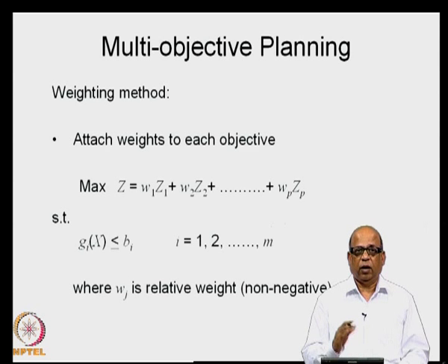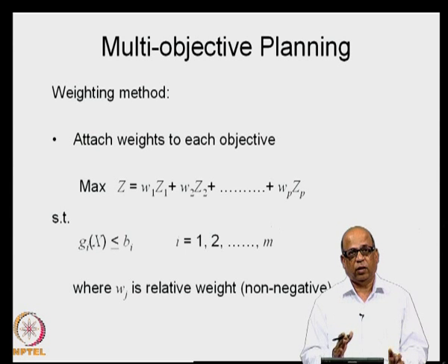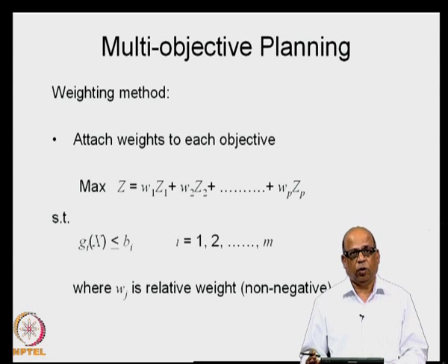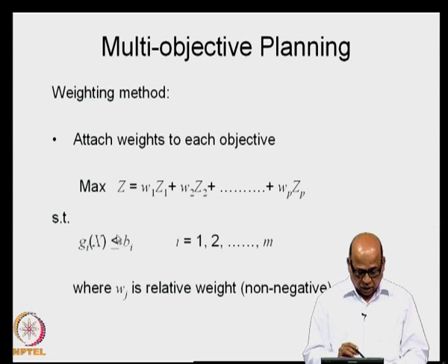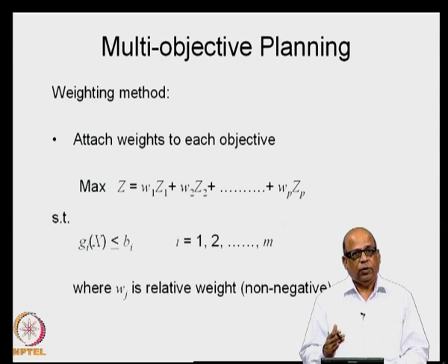For example, you may set a higher release as a constraint based on the canal capacity, lower release as a constraint based on the downstream requirement, and so on. So, these will always remain the same, irrespective of whether you are maximizing your hydropower, maximizing irrigation, and so on. So, these constraints are independent of these objectives, and they will always remain the same irrespective of how many objectives you consider. So, Z1, Z2, Z3, etc., these are all objective functions to be maximized.